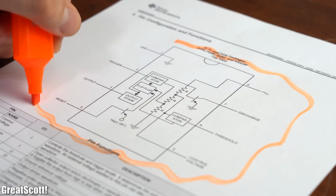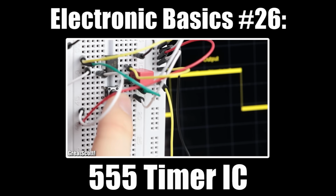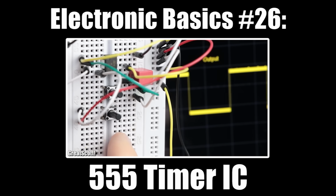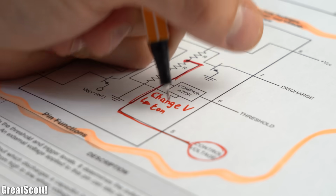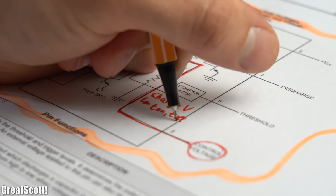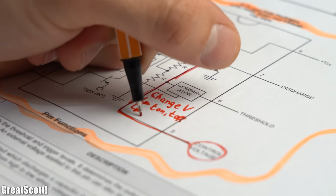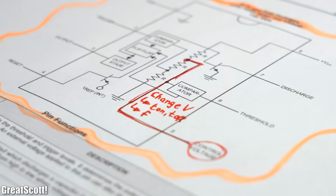But when we think about the internal structure of such a 555 timer, which you can learn all about by watching my video about the topic, then it should be clear that the audio signal will not amplitude modulate the carrier wave, but instead only change the on and off times and thus the frequency.